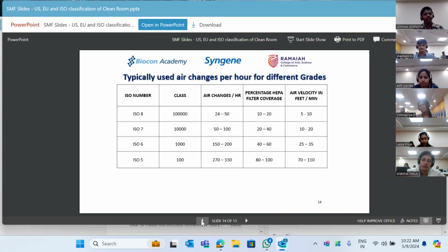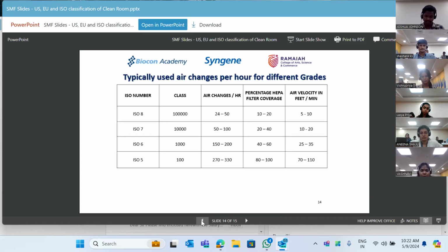Anything which the team wants to know from me on the various classifications? Sir, the percentage of HEPA filter coverage, that is 10 to 20% or what, sir? That is for ISO 8, 10 to 20%.